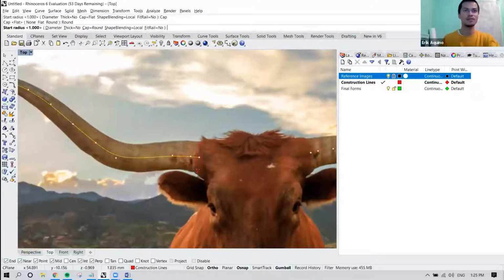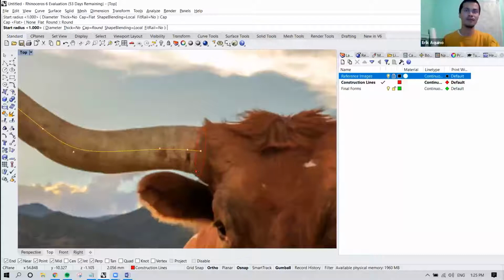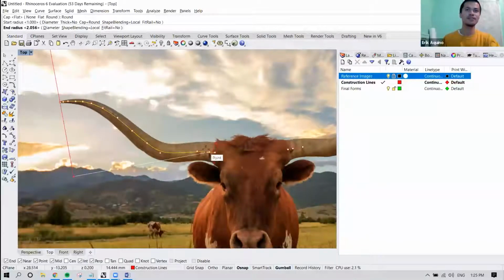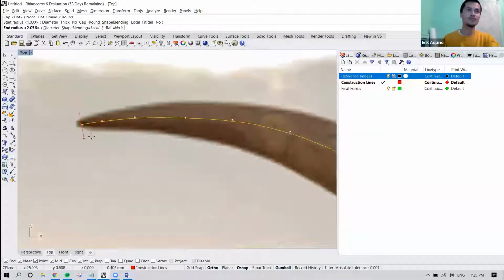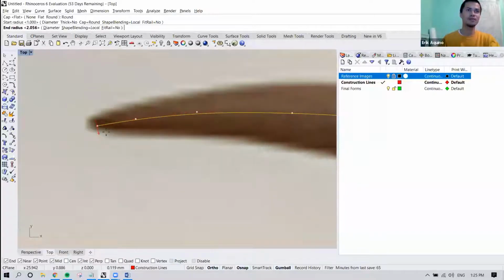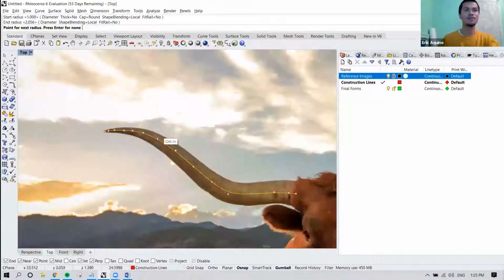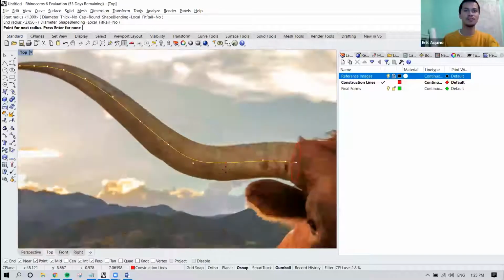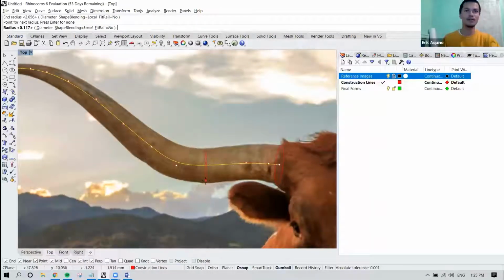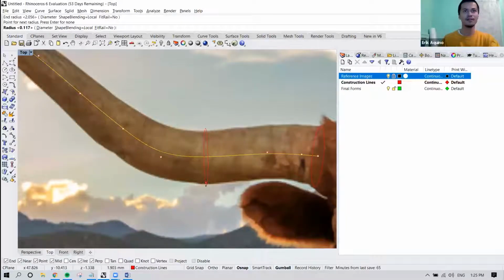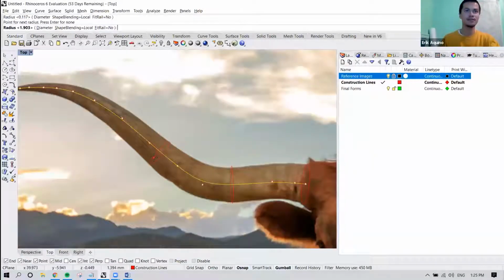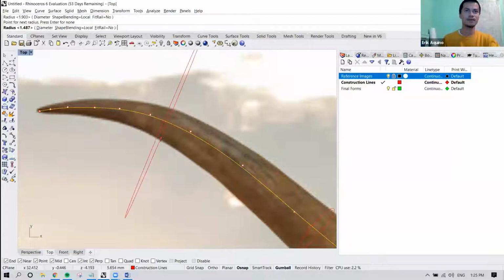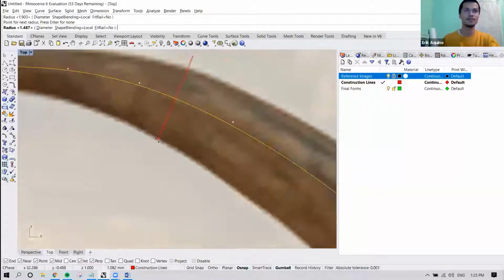So now when we decide to start clicking our curve cross-sectional profiles, it'll determine the first circle, and then we'll go to our second, which will be a lot smaller, so you'll want to zoom in, click, and then from there, once we've determined the two extents, we can go throughout the profile and add some more just to be more accurate with the shape of our horn. So I'll add a few in between that. This one's a bit difficult. Okay.